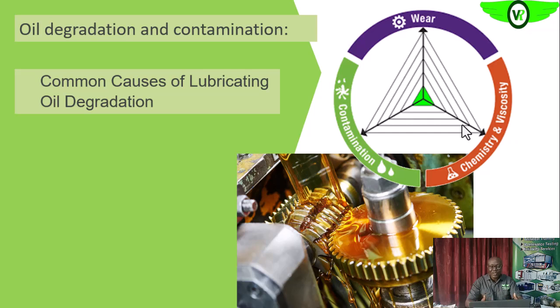Remember, the more wear particles we have in the lubricant, the more it indicates that there is a part inside the equipment that is wearing fast. So further analysis of the wear particles, that is, when we carry out wear particle analysis, as we will see later, we will be able to determine which of the component parts in the engine or equipment is actually wearing.